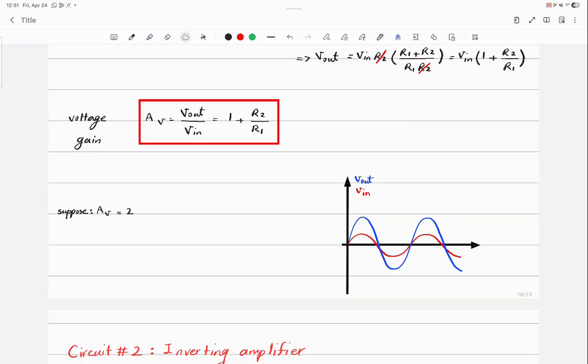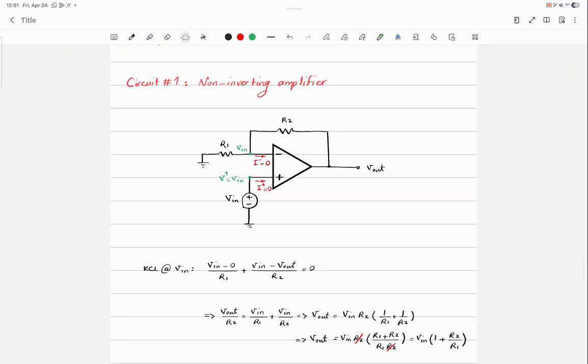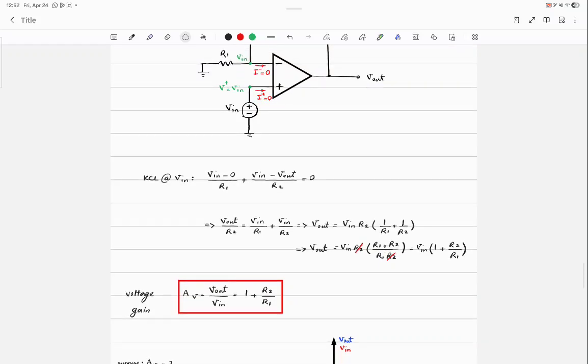Any problem? Okay. So that is the non-inverting amplifier, one of the very useful amplifiers that are built based on operational amplifiers or op-amps. Now, if you get this circuit on your third exam, I will talk about this when I'm doing the review of the third exam as well, but I want you to remember that. The natural way is to do all the assumptions, write a KCL, 2-3 lines, and then find the gain or the output voltage.